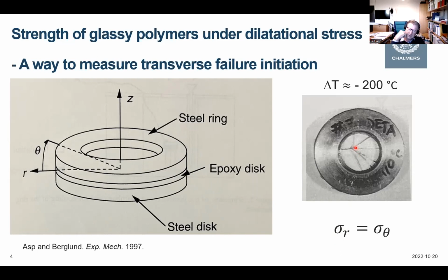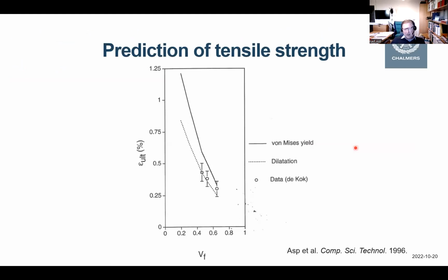Of course, we need to consider the change in the dependence of strength CTE on temperature, but this can be done. So with this, one can actually apply that on thick-ply composites and compare that to data that you have for those, and you can actually see that with criteria like this, one can predict failure, the transverse tensile strength of these composites.